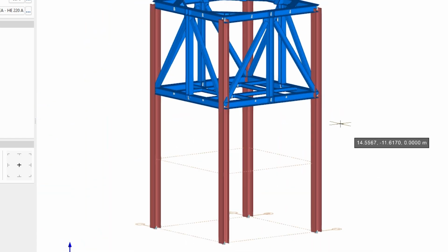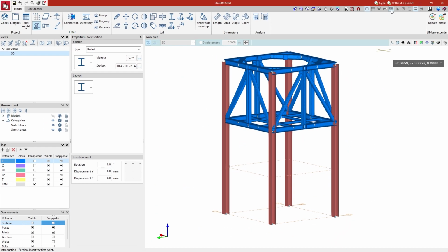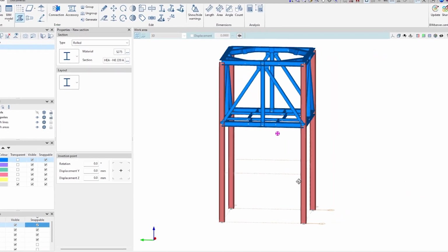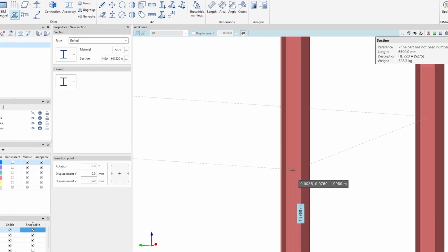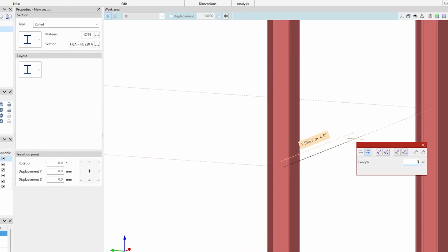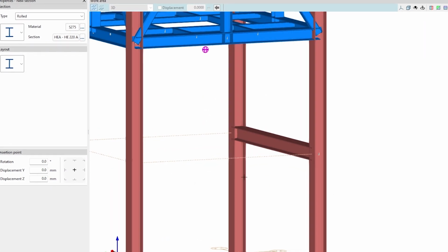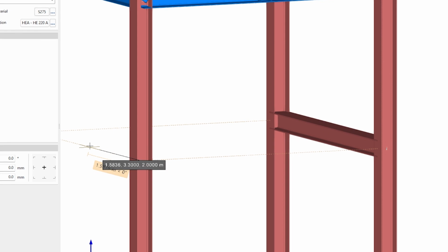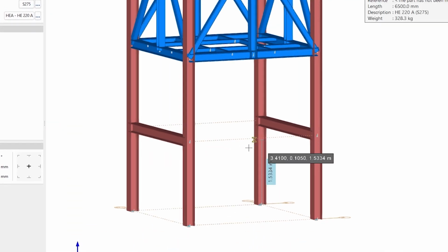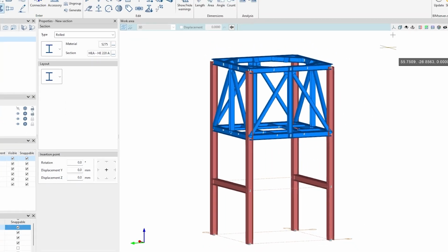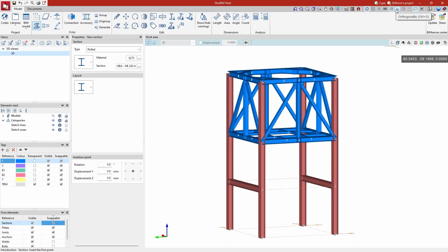Another useful option is to click on Allows for dimensions to be defined upon introducing each element, in order to enter the length value of the section when it is entered. On the other hand, the orthogonality option forces the direction of the section when it is entered.